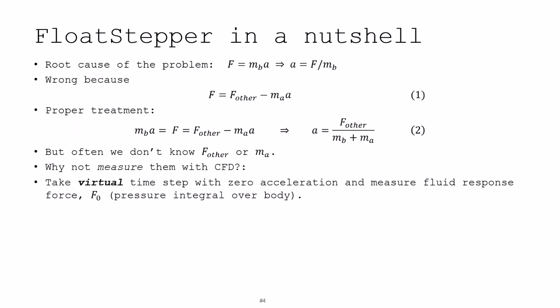And the way we'll do that is to first take a virtual time step, so not a real time step, with 0 acceleration of the body, and then measure the fluid force response. We will call that F0. That's just, in simple cases, just the pressure integrated over the body.